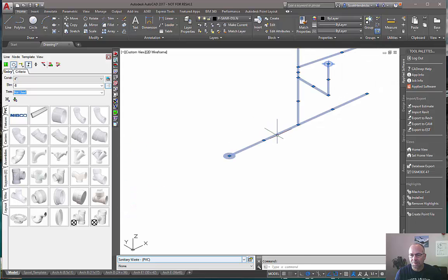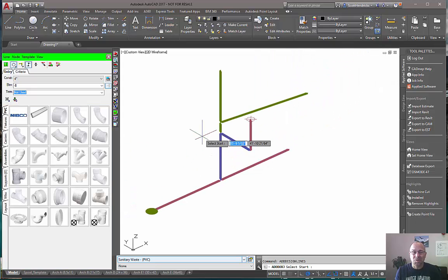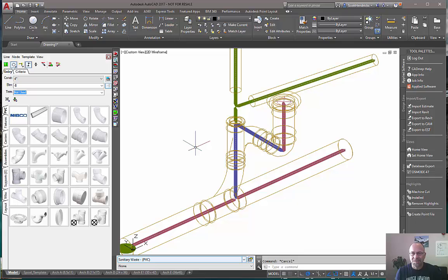Let's take a look at this one over here. We have a similar situation, except I have a wet vent involved in here, making it slightly more complicated. As we fill, we get the same thing as last time, but now we have two problems. I have a Santee that's not filling. We could place this in here and solve one situation, but then we still have the other situation up here. And in this situation, what I want is a Santee. I don't have a street Santee. I don't have enough room to put a regular Santee in.